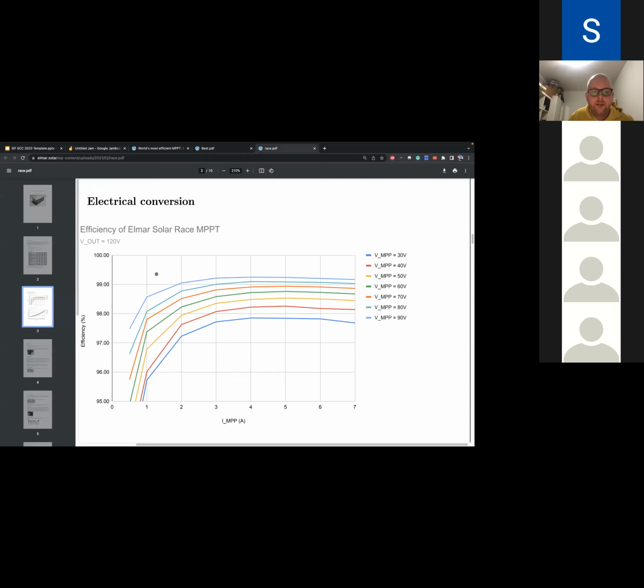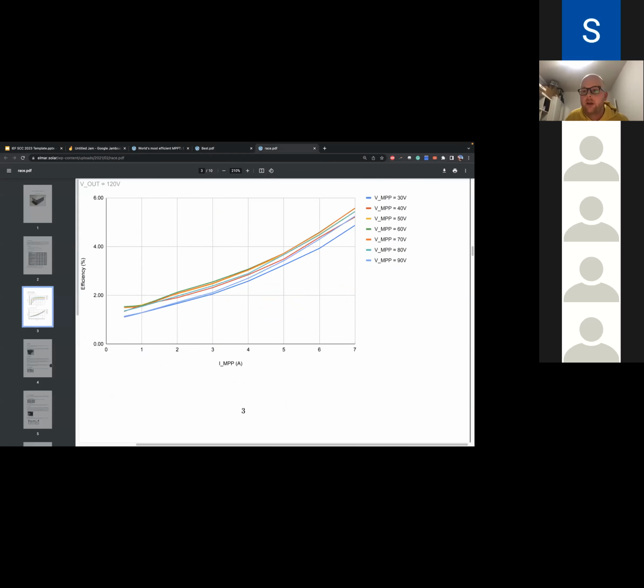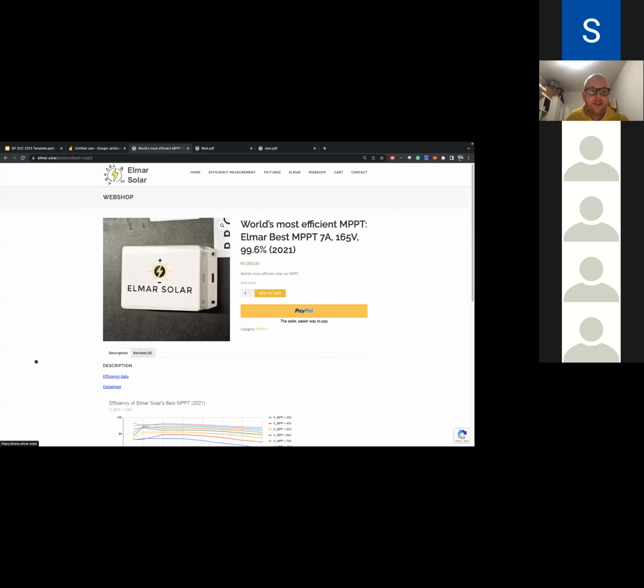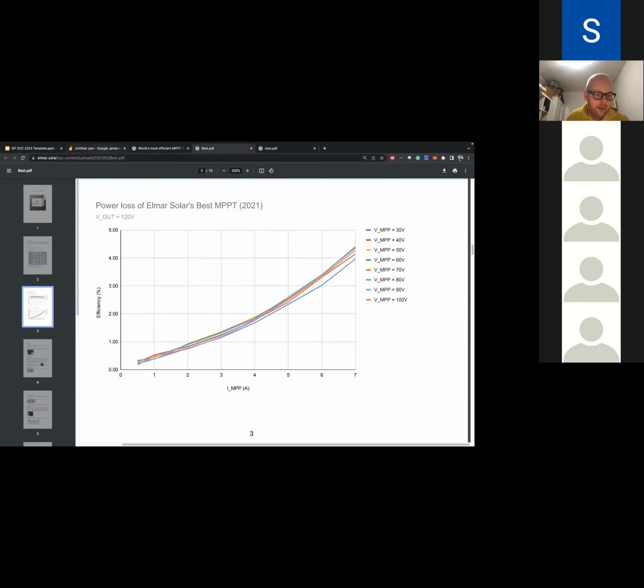And therefore you get this standby power consumption of 1.5 watts. That's mostly because 1 watt of that 1.5 is because you're shorting the capacitors in parallel with the switches that are parasitic, so you cannot really get rid of those capacitors.